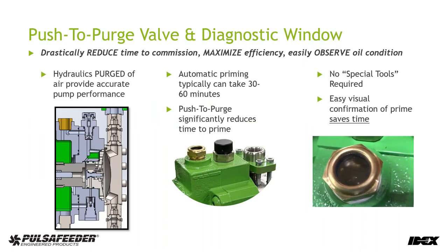So the push to purge valve and the diagnostic window. You may have heard me talk about solid hydraulics, but what's super important is that the hydraulics are solid, that there's no air in the hydraulic side. When I say hydraulic side, I'm talking about that area of the pump that provides the hydraulic fluid that drives this diaphragm forward and gives that process flow on the reagent head side.